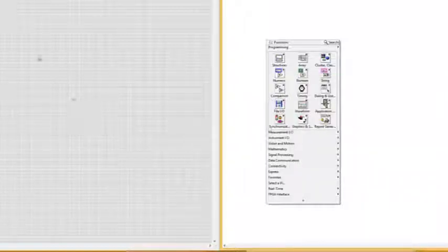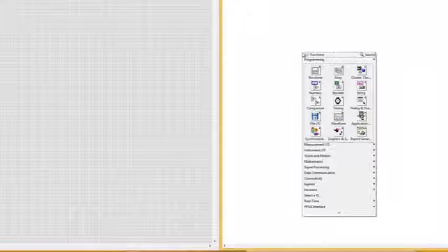For example, if you check the functions palette, then we have this add function. This add function can't be placed in the GUI. For example, if I want to design a calculator, you don't want to know what's the coding behind it, you just want to get your value. So all those functions which have some user interaction are in the controls palette, while in the functions palette we have each and everything. So in simple words, the controls palette is a subset of the functions palette.